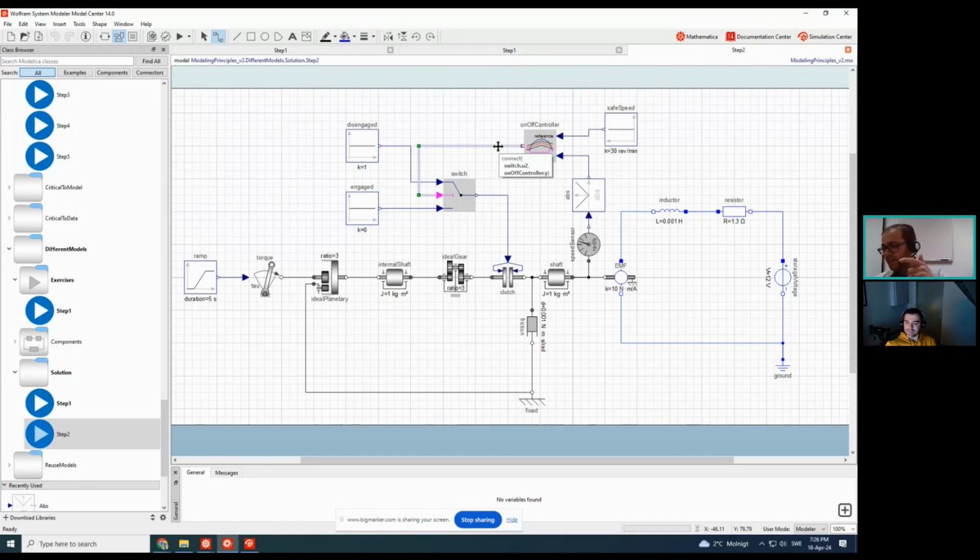So it tells either be on or be off. And then we have a switch flag mechanism that says, okay, now time to go or time to stop. And then based on this flag, we have a switch which switches between two different inputs. If the speed goes beyond a threshold, then disengage. If the speed is within the threshold, then engage. Right? So those kinds of logic one can think of and expand their models using these real outputs.